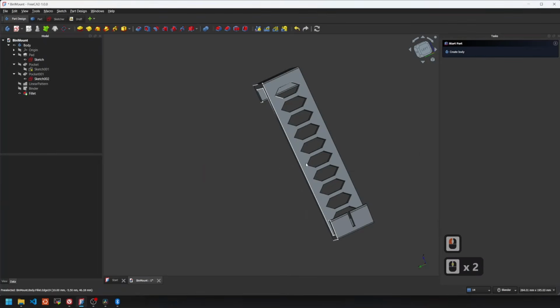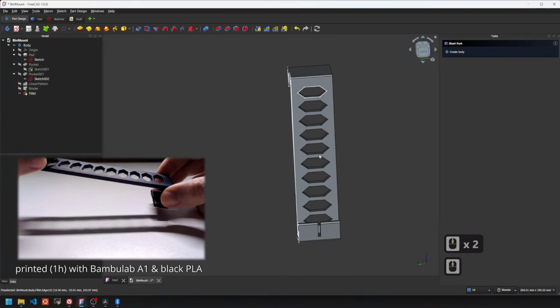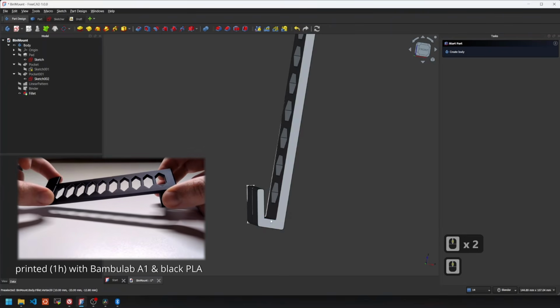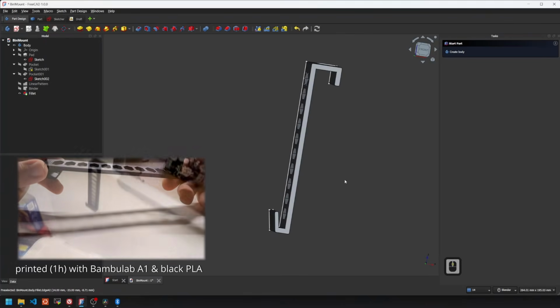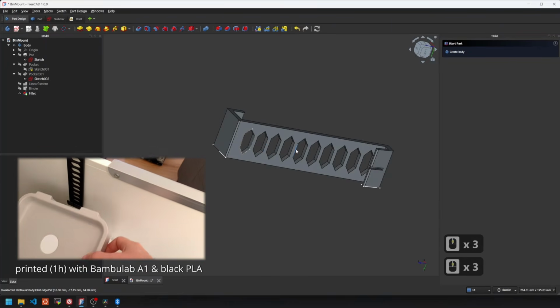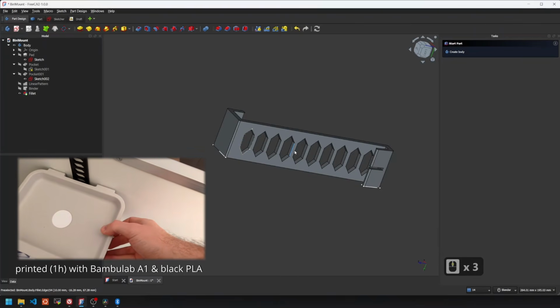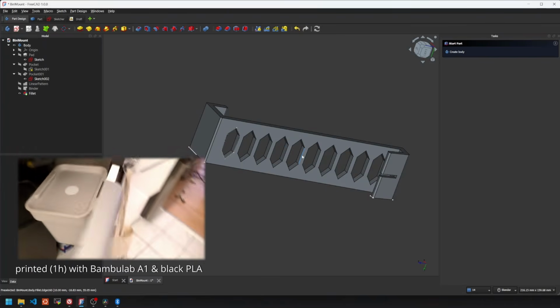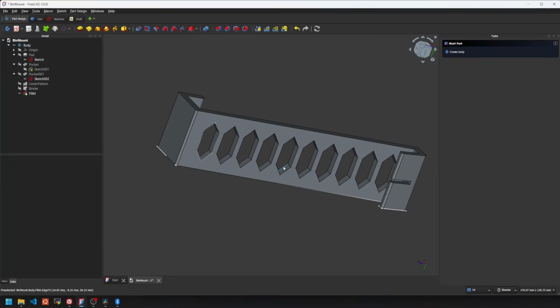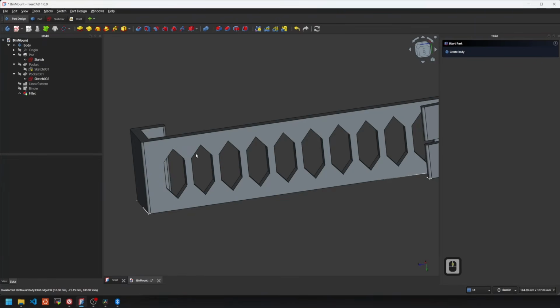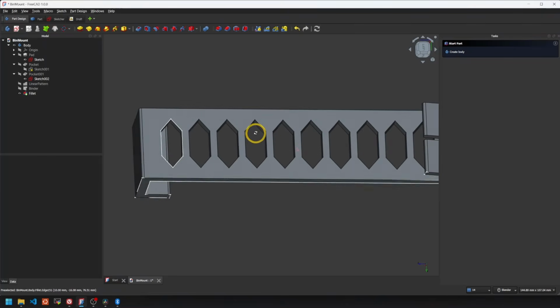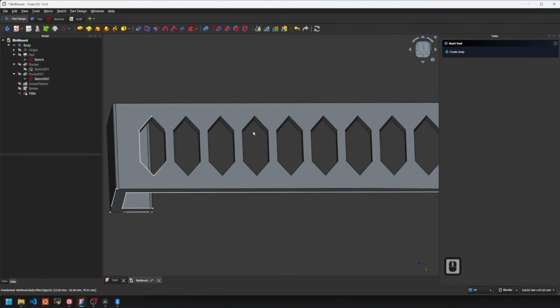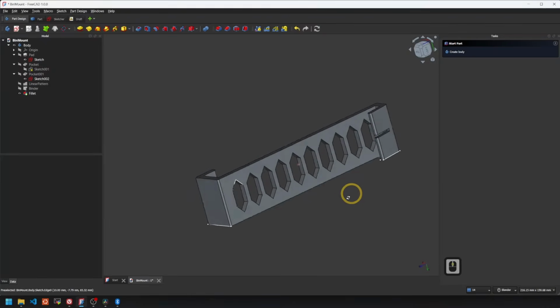This is the updated design. As you can see, I added some cutouts. I reduced the distance here, and I added also some rounded edges. Now those cutouts, obviously they reduce the printed material, but they actually add print time because they are more complicated to print. I was thinking what kind of shape could I use for a pattern. I decided to go with this one because I can print it without any support structure. And also it kind of looks cool.